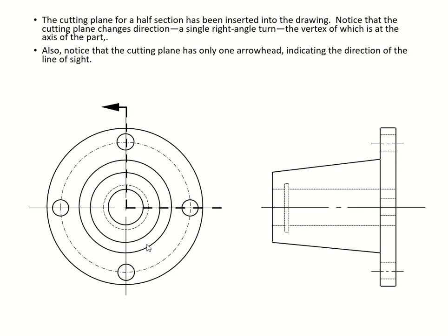So if you cut half of this, you can either go here or here. Sometimes you can also start on the other side, doesn't really matter. And you can also see it's not the regular cutting plane. It's pointing there, and here is pointing inside. So you can see it going that way, and then turn the direction here, this way. Cutting plane changes the direction.